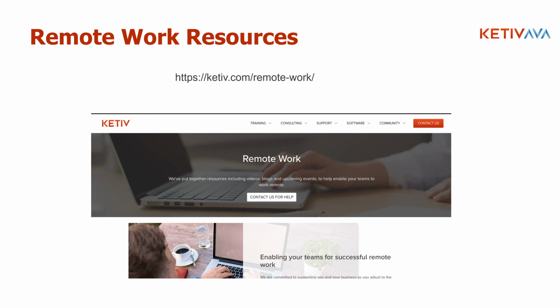You can technically use attributes in iLogic because you have access to the entire Inventor API through iLogic, but there are times, because of the way iLogic works, that there are certain things it kind of hiccups on, or it may be easier just to do it in an actual VB.NET routine or DLL. I do have some customers, because iLogic does allow you to take a precompiled DLL and import it into iLogic to use it. You have some customers that do that. So that might get you around some things, but it depends on what your needs are.